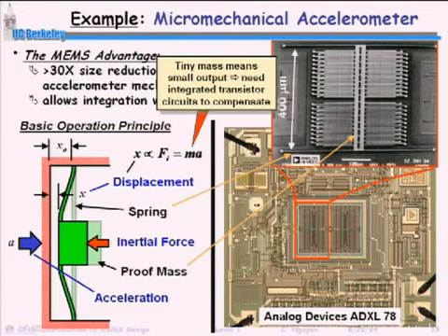But you see a problem with this? The scaling factor for that acceleration, right? You want that output variable to be as large as possible because you need it to be above the noise of the sensing electronics. But if I'm going to scale that mass, if I'm going to use MEMS to make that mass smaller and smaller, my scale factor suddenly has gotten smaller and smaller, and now I can't sense as much acceleration, right? The minimum detectable signal has gotten worse because I made this thing smaller. Okay? So this is a case where smaller is not better, smaller is worse, and much worse.